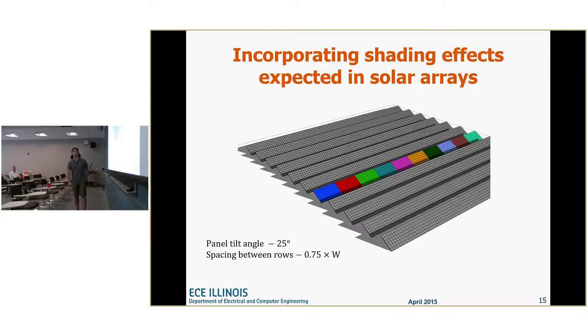Okay, so now we can add a third source of mismatch into our array and model how our row of panels would do if it was in an array of panels. Working off some of my previous presentations, here I'm incorporating self-shading and diffuse masking, so at certain times of the day or year, forward rows begin to shade the rearward rows. If the row we've been modeling is now part of an array, we could have a third source of mismatch. I'm just assuming these values.